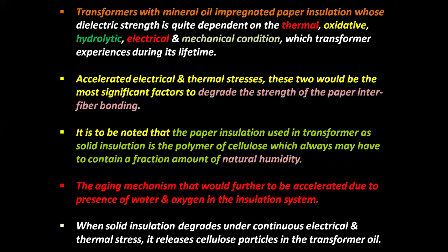Transformers with mineral oil impregnated paper insulation, whose dielectric strength is quite dependent on the thermal, oxidative, hydrolytic, electrical, and mechanical condition which the transformer experiences during its total lifetime.